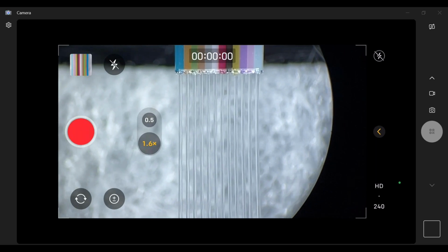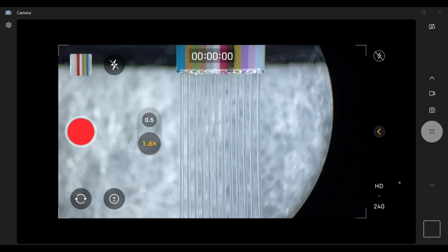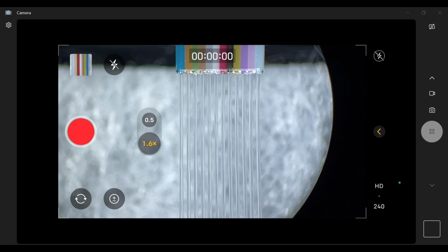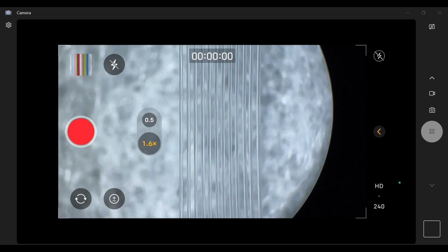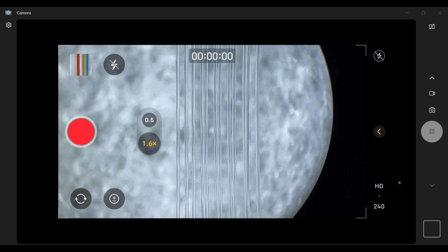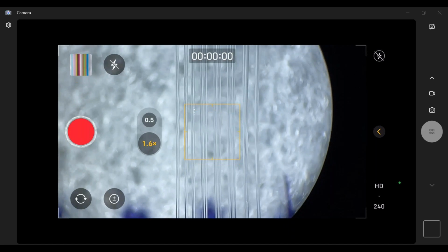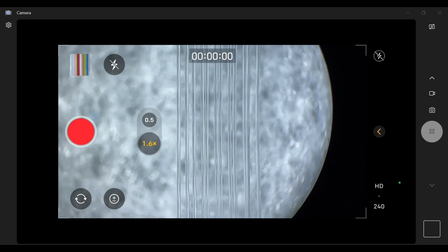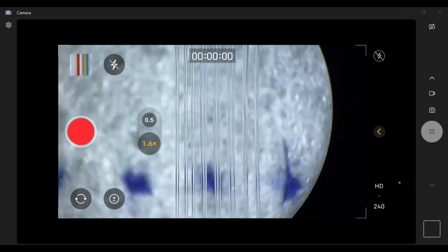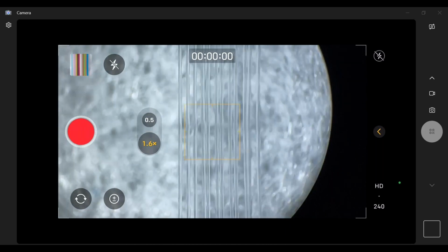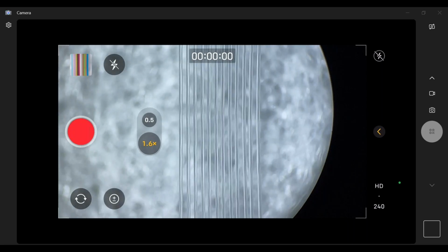Now, I always tell folks this: when I'm prepping the fiber, before I ever get to the cleaver, I want these fibers to simulate teeth coming out of a straight tooth comb. You want all fibers to be parallel. You don't want them touching. If I go back and look on down the line here, you can see a couple of elements, what I would call separations, entanglements. And this can be a result of many, many things.